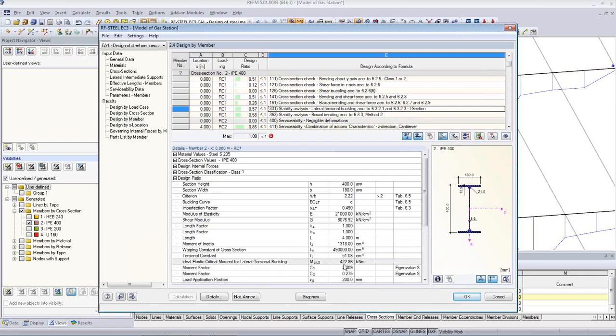Lateral torsional buckling. So now we're back to 422. It makes a real big difference whether you have an intermediate support or not. Very powerful feature. This time stability wasn't quite so dominant, but if you have stability as the controlling design situation, it will save you tremendously. The next question, or maybe there's another question that says, what about those set of members and how that works?